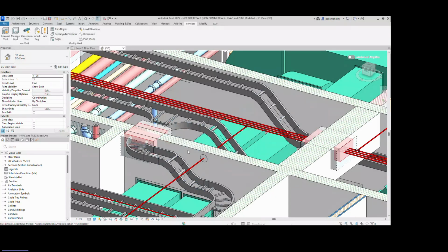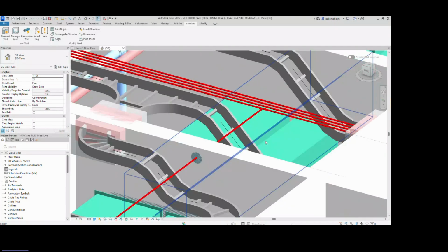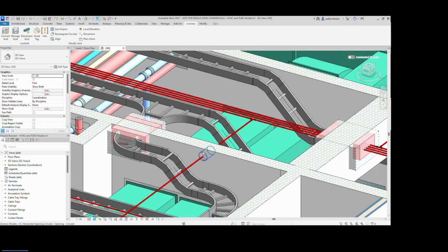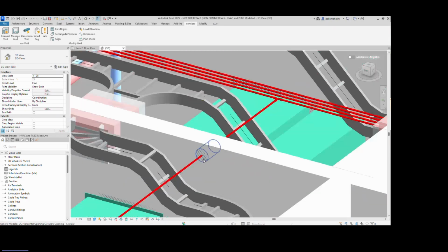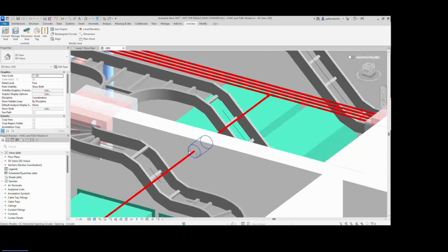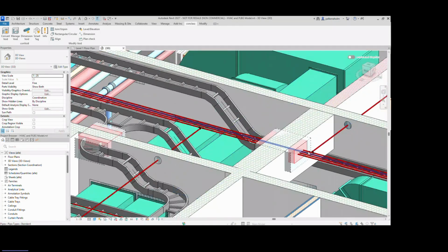And as you can see, here is a new clash marker, also right next to me here, but there was no clash marker because there's already an opening. So ConVoid already considered the ConVoid placed openings. ConVoid sees there is a pipe penetrating the wall, but since there is an opening placed in this location, ConVoid sees this clash as resolved or nonexistent.